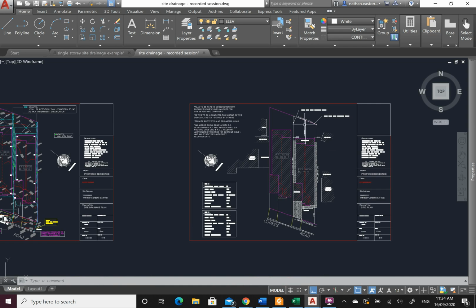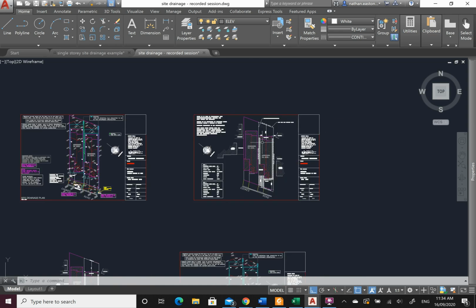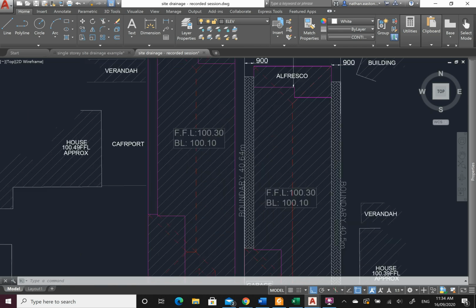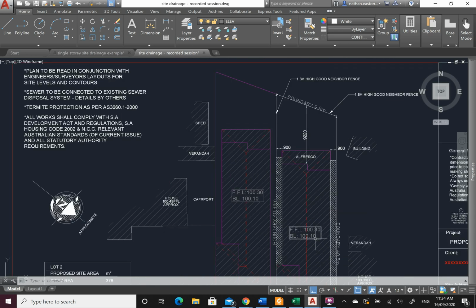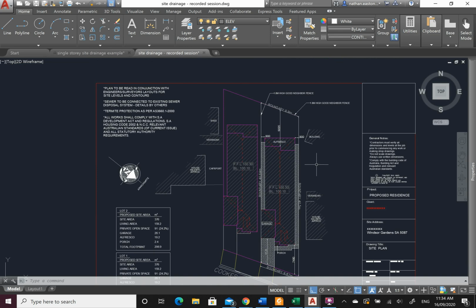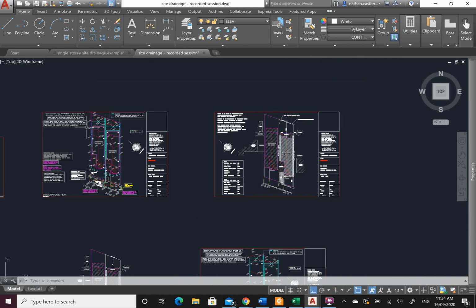In here, if you have any retaining walls, you will note where retaining walls are. You've got a few different other things in regarding to the site that you might have to add. In our case, because our levels are the same, we've got 200 mil difference that we can get up to without the use of retaining. Once we surpass that, we have to put retaining walls in. But these are the plans that have to go to council for you to get your planning approval.